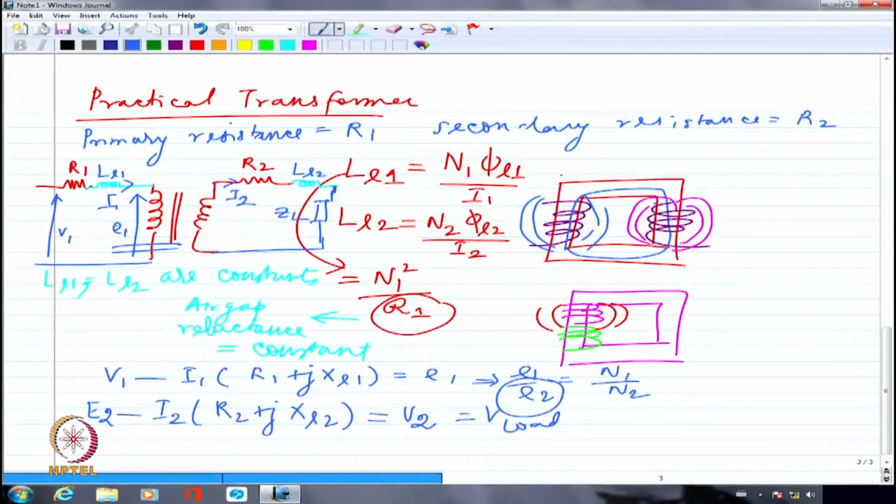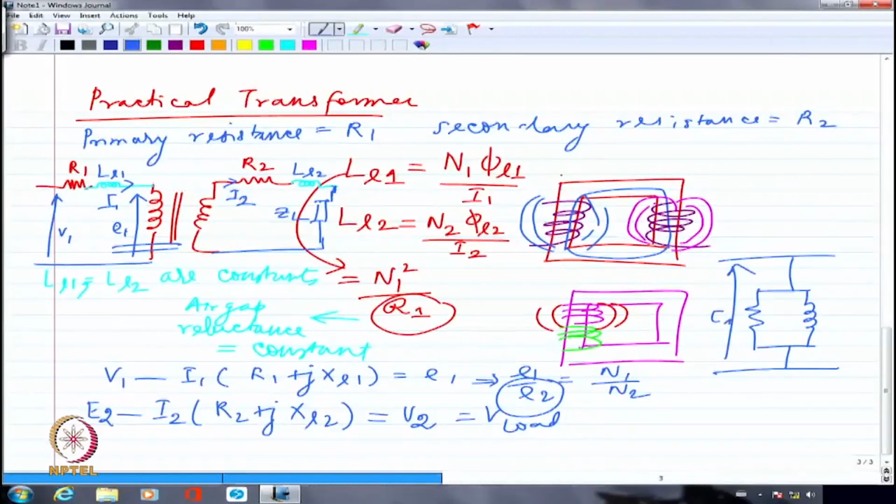So please recall that, and for that how we represented was to have a resistance and a magnetizing reactance which would come parallel with each other for whatever is the voltage that is coming up across this. And the voltage that is coming up in this case is E1 and not V1. That's not V1, that is E1, because the flux is established, the mutual flux is established corresponding to the self-induced EMF within the primary coil, which is linking with the secondary coil as well.